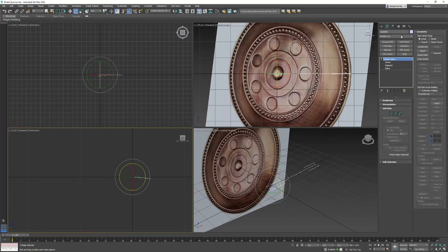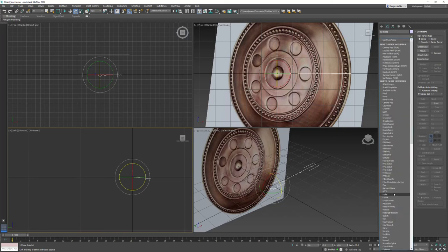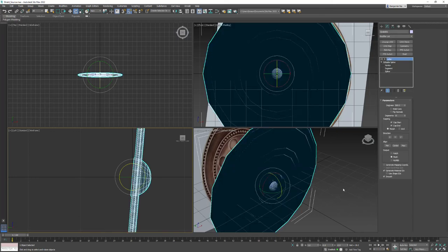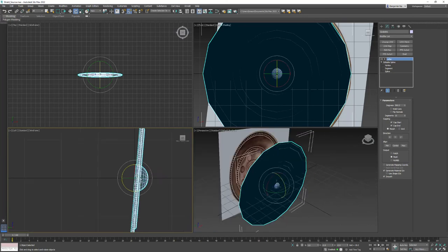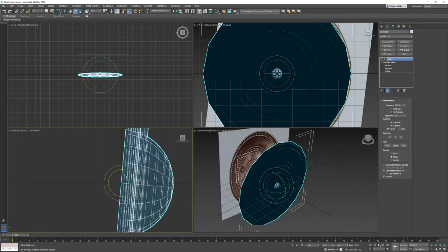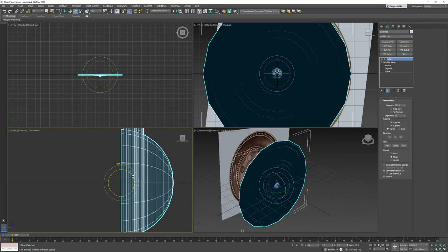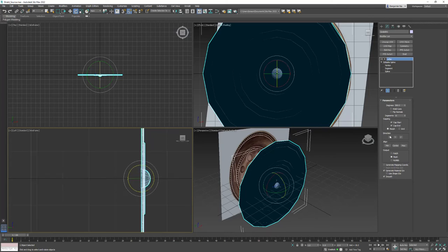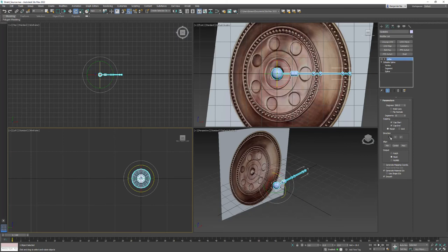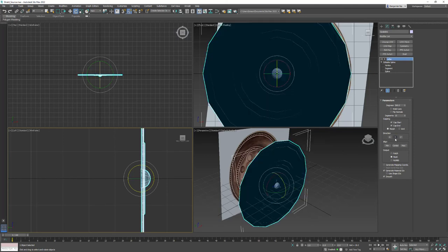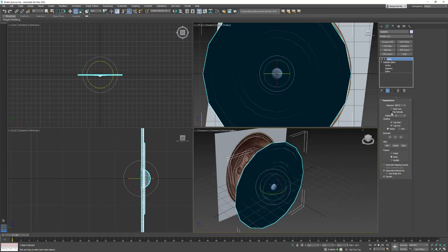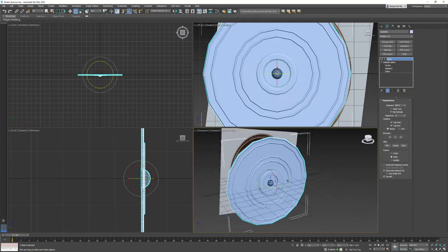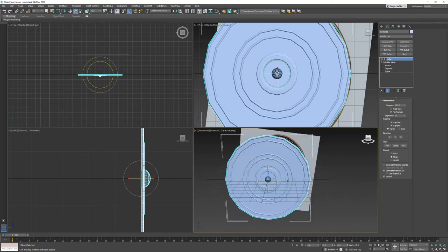So let's now put a lathe on it and see how well or how bad this went. All right, so it's definitely weird looking. I guess I didn't go fully 90 degrees when I rotated it. Let's try changing the direction. Definitely not X. Y. Is it inside out? Let's do flip normals. Hey, flip the normals and that's it. That is what we're looking to get, something like that.